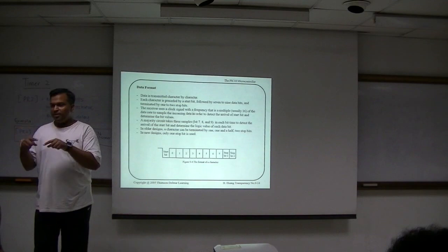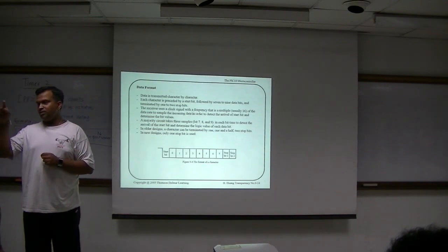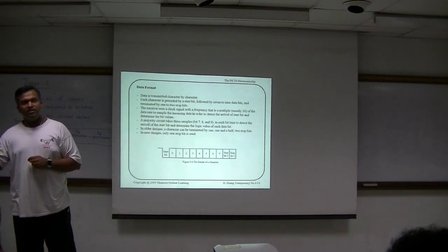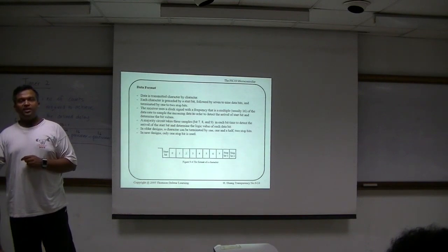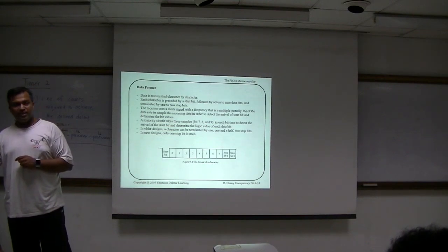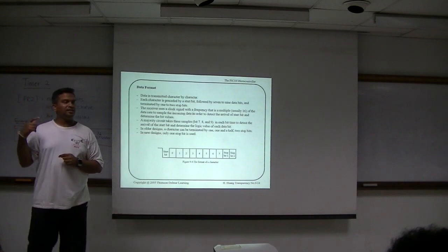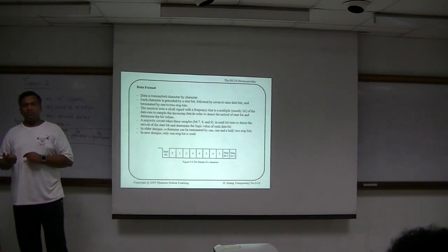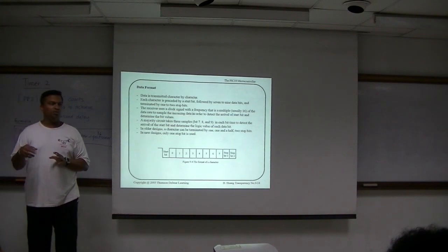If you look at the properties of your UART, you can see the baud rate by default will be 9600, and the data size will be 8. But you can also set it to something else. There will be some applications where you need to send more than that.